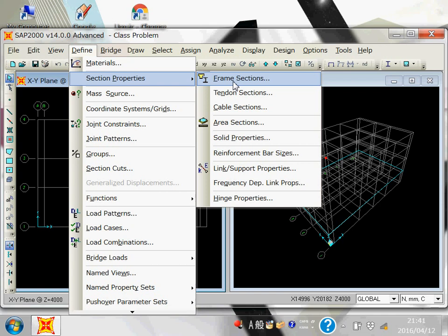If your reinforcement ratio is more than 8% in the column, it will show overstress and the color will become red. For example, the actual size of the column you need is 600 by 600, but you have provided 300 by 300 because you don't know.